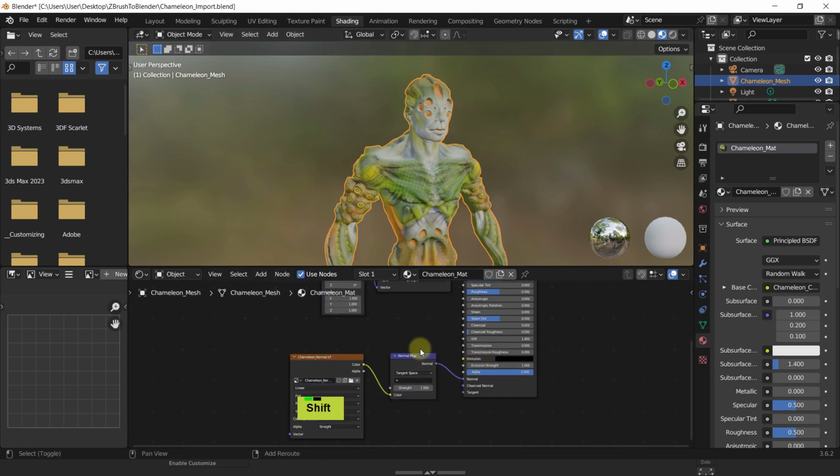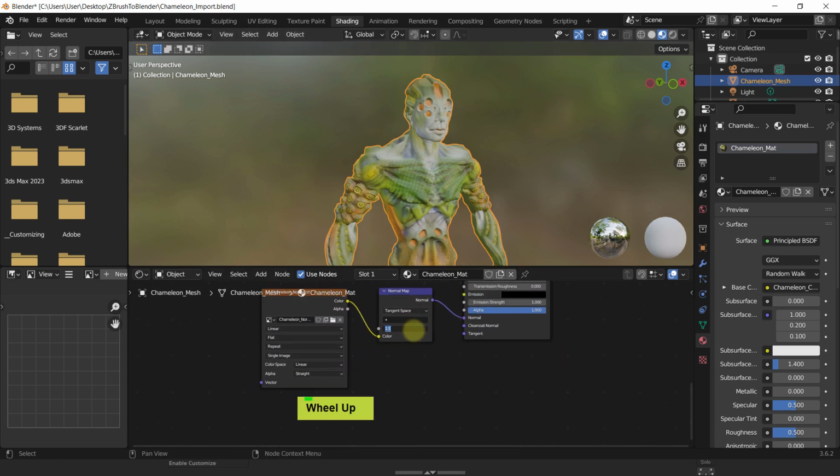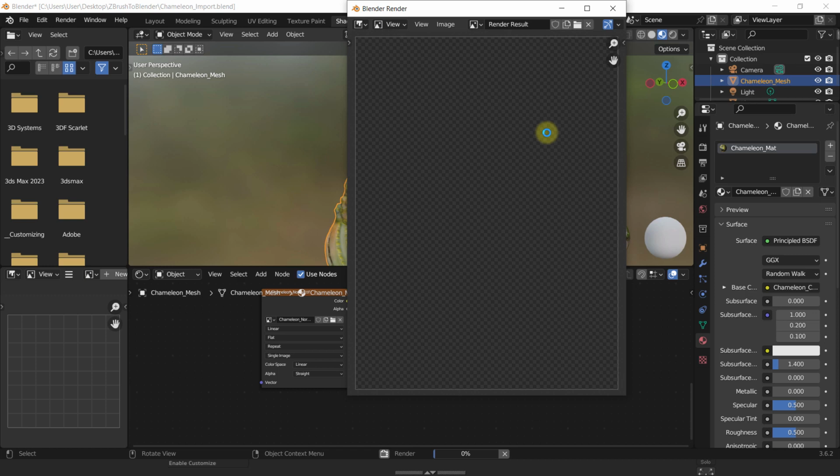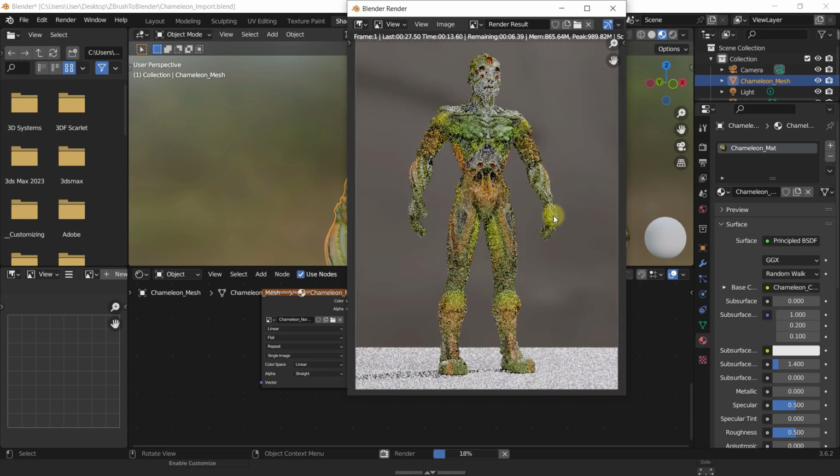Okay, so strength set to 1, and I will quickly just restart the render and see it for myself. So testing can take up a lot of time. This is why it's better if you just reduce the stress on the machine and keep small sized renders with low quality settings, just for testing purposes, of course.